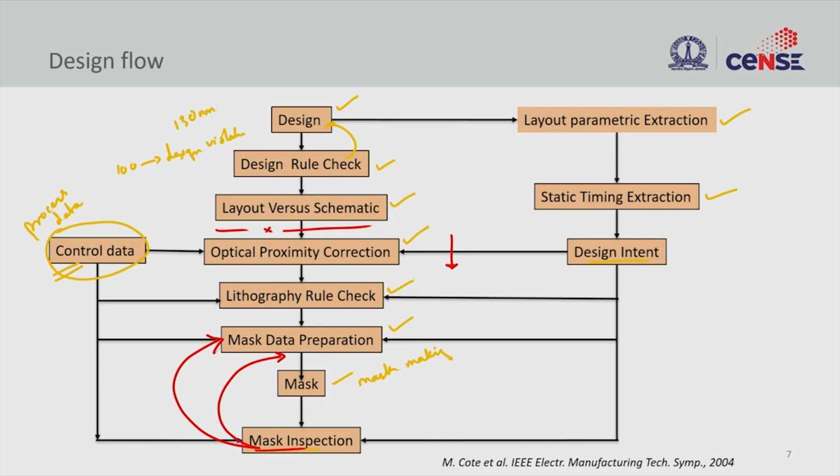But the interface here is this design intent, right? So what is the purpose of my circuit? You share this detail with the litho team, and they are going to use those data in order to do the timing analysis after doing proximity correction, or in some cases it is given back to the designer to run the timing analysis and also window and so on.